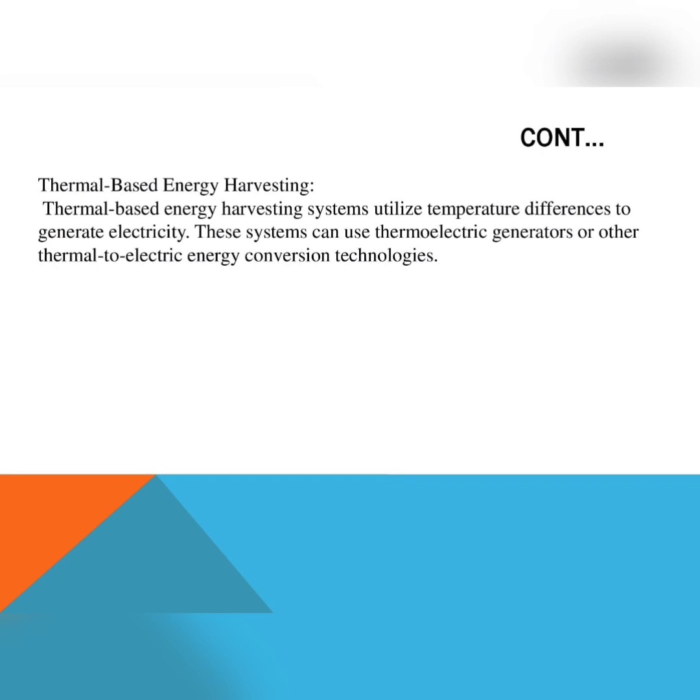These devices utilize the Seebeck effect, where a temperature gradient across a thermoelectric material generates a voltage. The power output depends on factors such as the temperature difference across the generator, the size and the efficiency of the TEG module, and the heat transfer characteristics of the system.